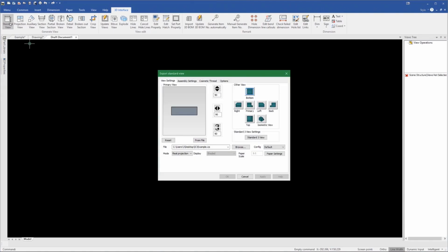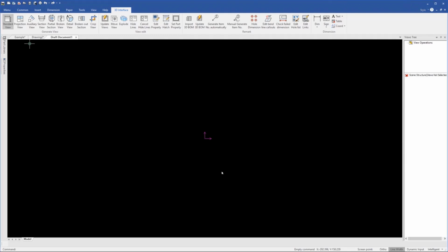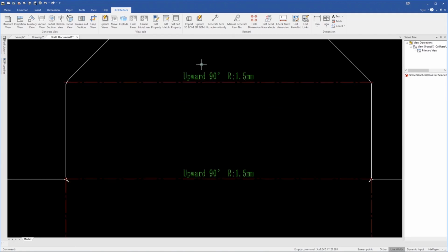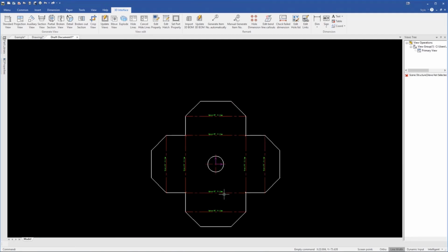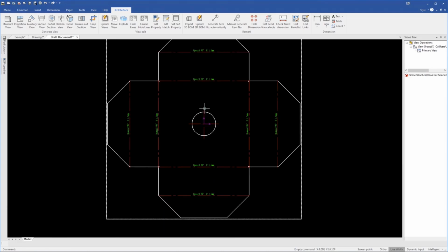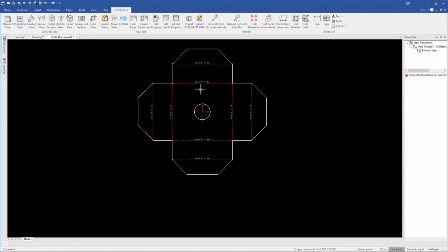For example, here in this case, if we just wanted a quick one-to-one DXF, we could go in here and do the unfolded view, and we'll choose the top view, or we can flip it here and then choose the primary view. Then in options, we'll bring in our bend lines, bend line annotations, and then click OK. Click to place our view, and it'll bring in those bend dimensions and bend lines as well, and they'll be on separate layers by default, so that we have those set up and we can just save as many different DXF versions from many different years to send them ready to go for laser cutting and so on and so forth.